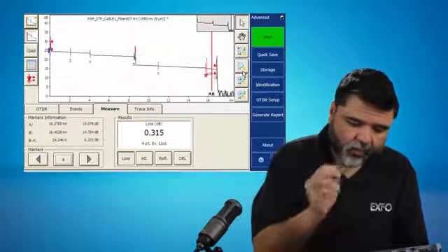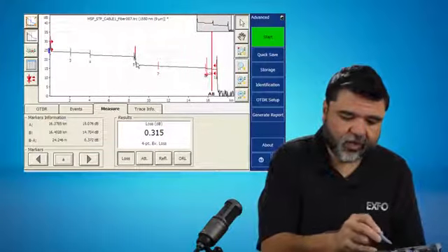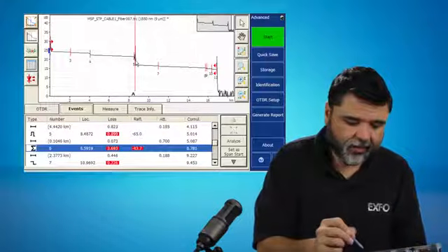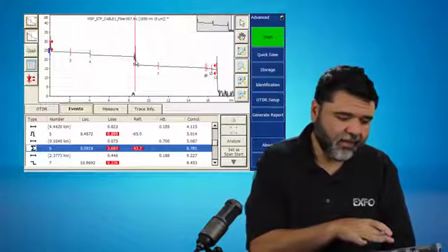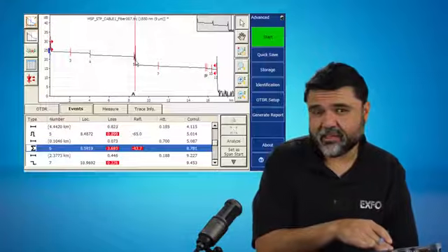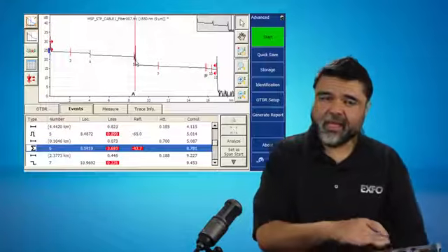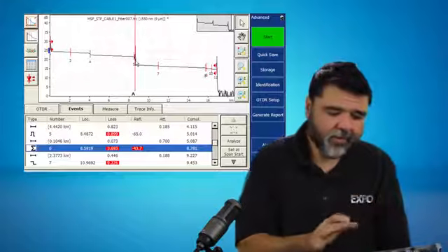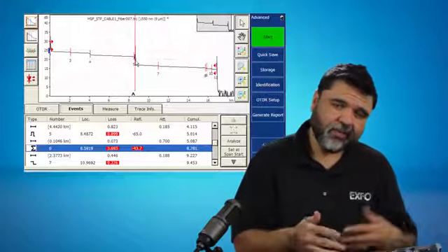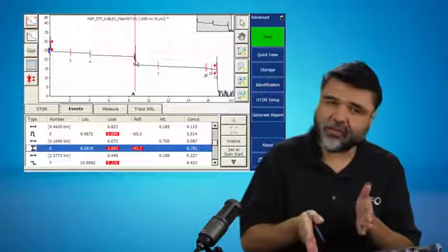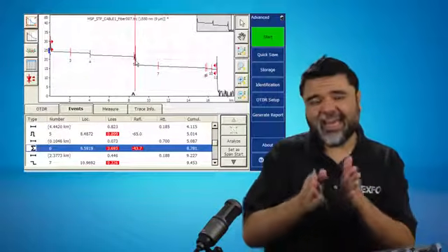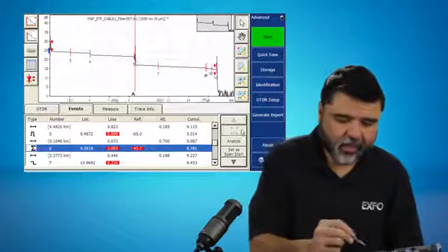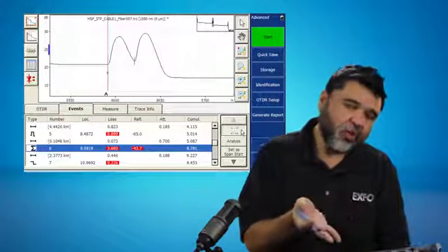And so within this network simulator, we actually have two connectors that are very close to each other. So I'm going to go ahead and select this particular event at 8.6 kilometers roughly. And if you look at that symbol at the left, you have that sideways M. That means that there's a merged event, meaning the OTDR software detects two reflective events close to each other, but cannot separate them to measure the attenuation or the loss of each of them discretely. So I'm going to zoom into it, and here's what it looks like.